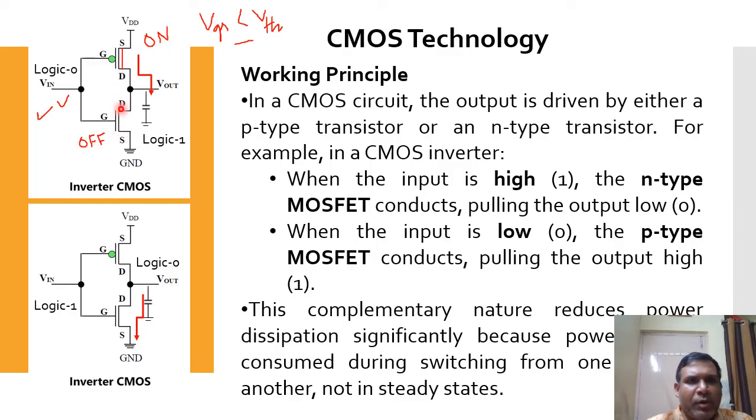As the N-type MOSFET acts as an off device, there is no direct connection with the main circuit. This N-type MOSFET will be isolated from the main circuit, whereas this p-type MOSFET will act as an on-state device and it will form a low resistance conduction path between the power supply and ground.